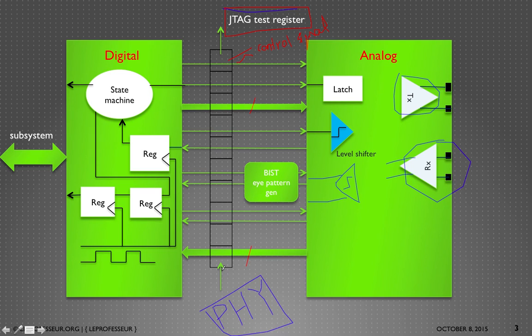So when the chip is running in test mode, the only thing you can do is observe the data from the JTAG test registers. You put the whole chip in test mode, and what is going out from these signals you monitor on your JTAG test ports. So you need to wisely and carefully select all those interface signals which are needed in JTAG test registers. That's one thing.